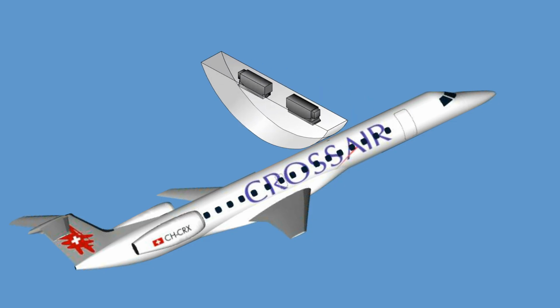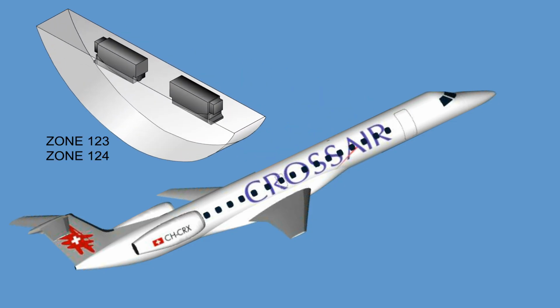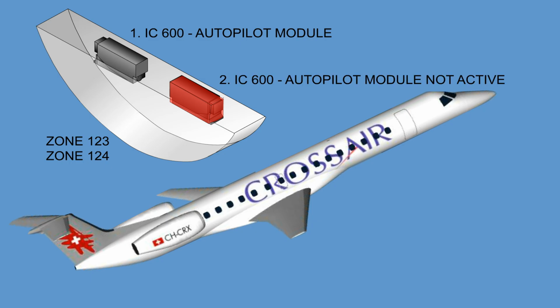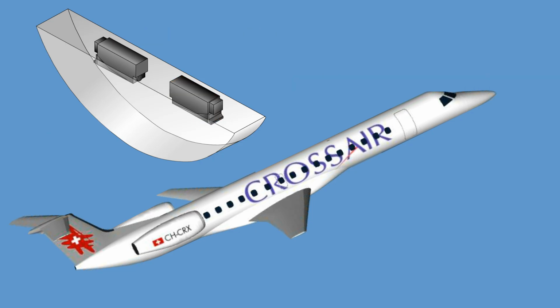The 2 Flight Director modules are housed in the 2 integrated computers, while only the integrated computer number 1 incorporates an Autopilot module. Optionally, the integrated computer number 2 can also incorporate an Autopilot module, but even so, only the left integrated computer Autopilot module will be active.